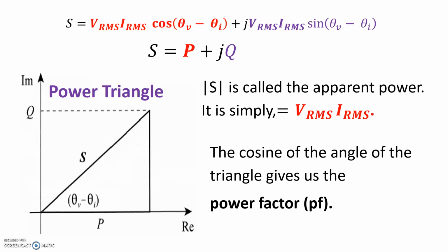Sine of theta v minus theta I has another name. It's called reactive factor, but we will ignore that for now. So we'll just talk about the power factor in a second. This particular representation of real power and reactive power in this triangular form is called the power triangle.